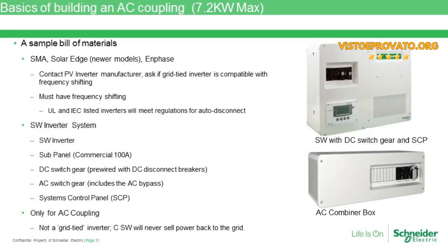So here's an example of just what a dual inverter system with the XW Plus would look like. The nice thing with the Schneider product line is we can use two of those conduit boxes underneath to help us manage the wiring, and that's going to just go up into the power distribution panel, or PDP, to the variety of breakers that we have up there. You can see that gold plate there in the background, and that represents the DC busing. So this makes things pretty darn easy to bring 1, 2, or 3 of the XW Pluses into a single power distribution panel, and keeps things pretty neat when you're putting the whole thing together.